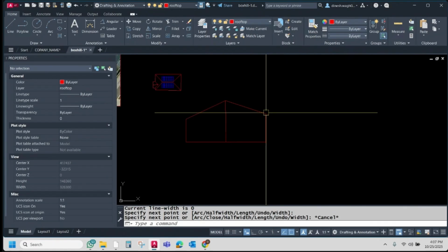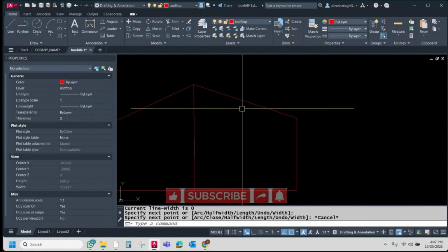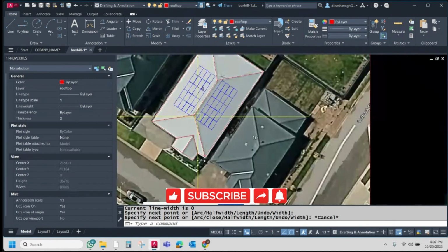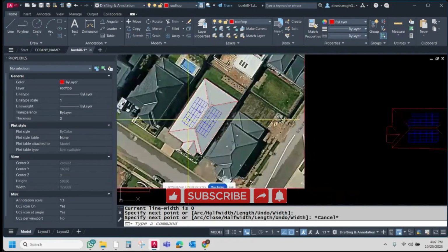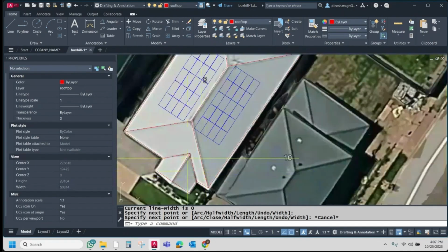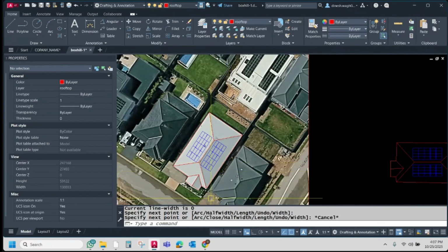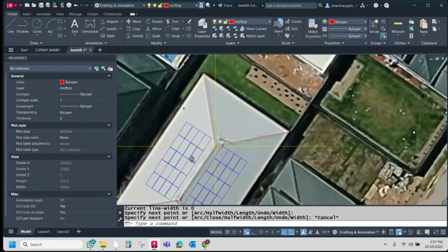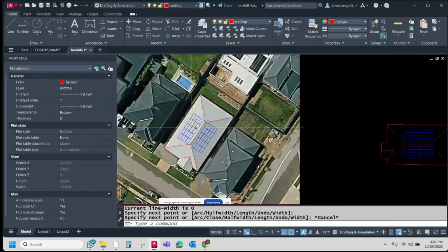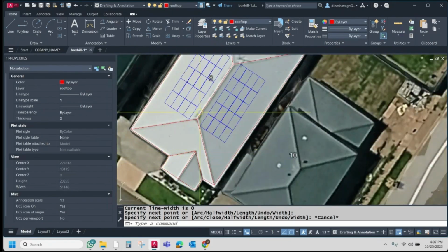This will indicate how long the roof is and how much angle there is. So when we are preparing the layout and we can't access the roof, I will measure this length first, then how far this point is from this part, and then how long it is from this wall to this part.